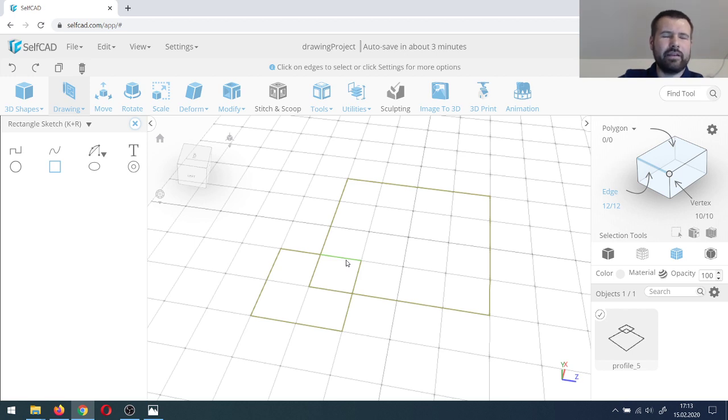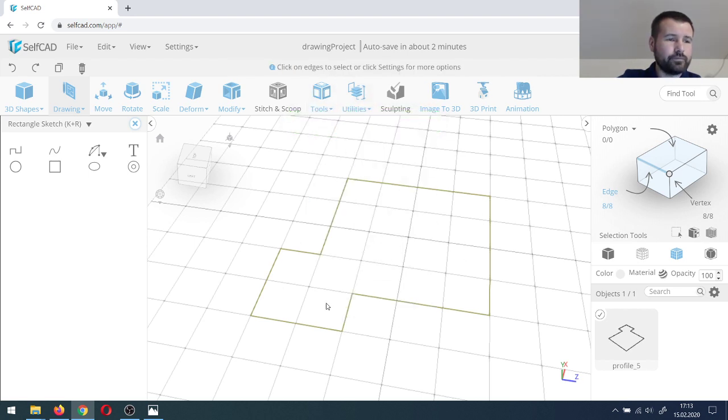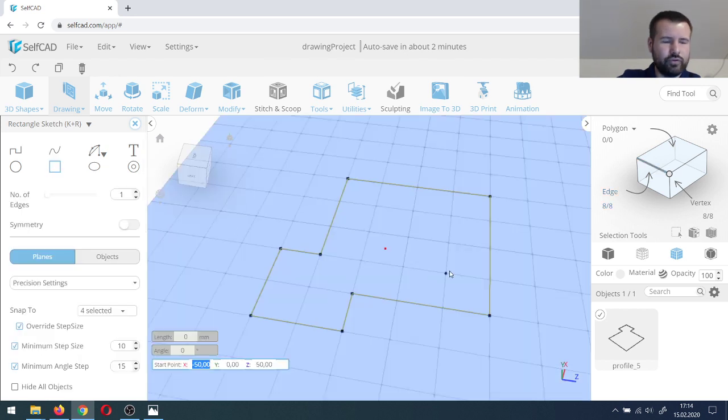We still do an intersection between those two rectangles, and we do it automatically. In other software, you might have to use a tool called trim to actually remove those parts. We do an automatic intersection, so you can just simply select by, for example, choosing edge selection from the right side panel selection cube, and you can just select them and remove the edges like that. And now if I would go to fill polygons, I would end up filling this, but I also want to show the other case, which was using eraser to actually generate holes.